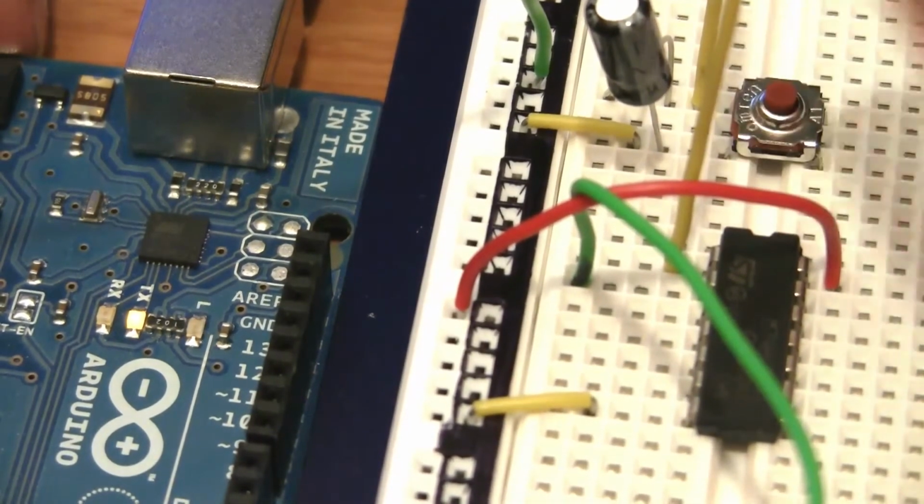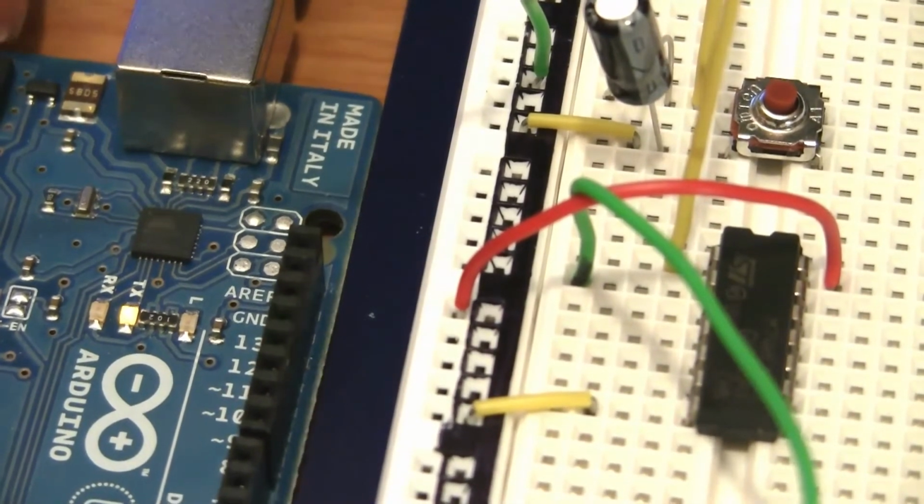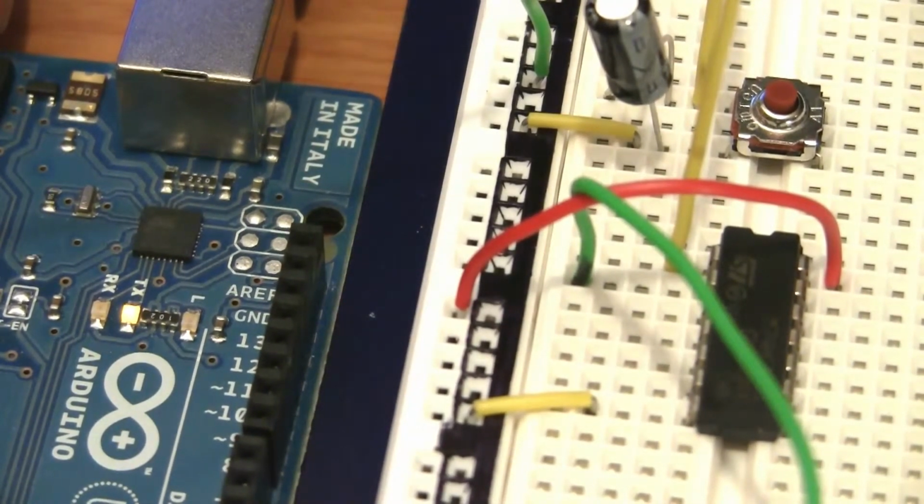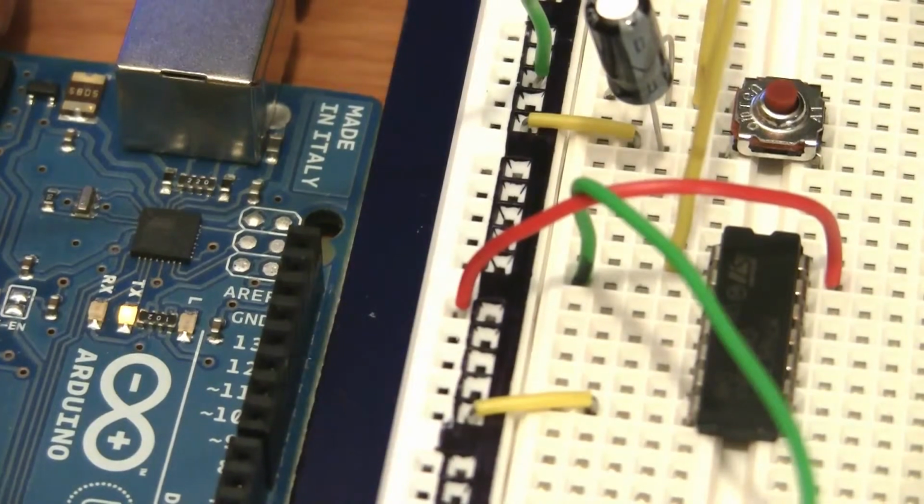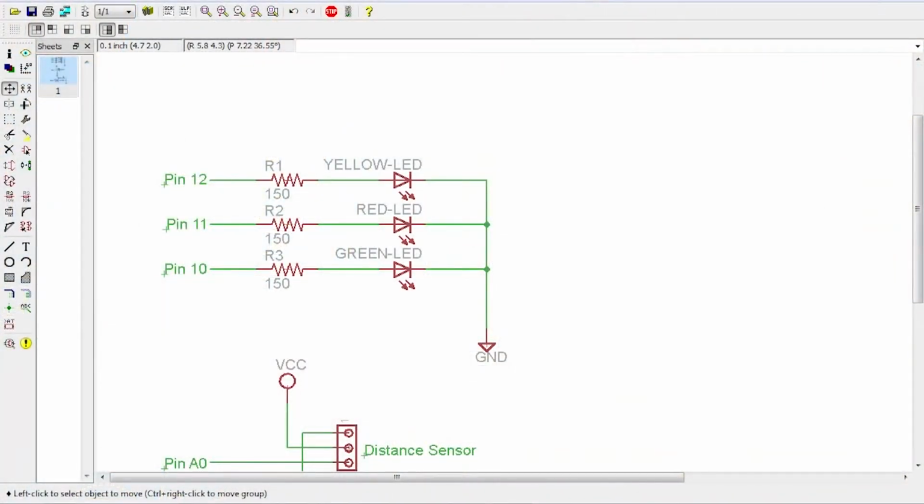Works perfectly, and we didn't have to do any software debouncing. Remember what a pain that was last time? And all we had to do was add 2 components to the circuit. Awesome. Now that we know how to debounce a button correctly in hardware, we can use it as an interrupt into the circuit without having to worry about any bouncing issues.